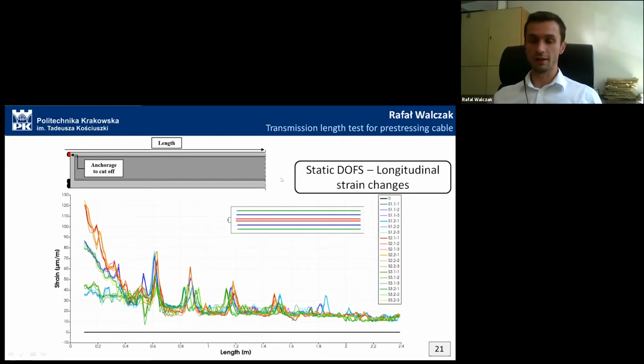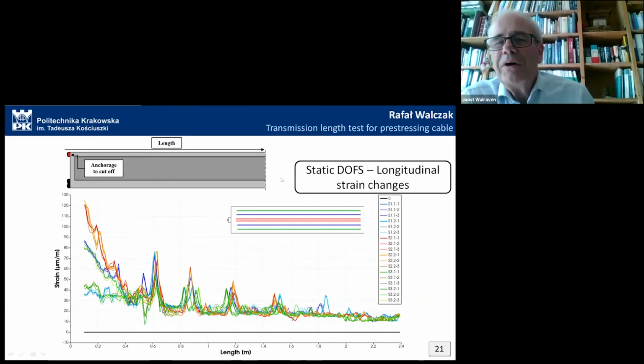And later on in the research, it is planned to study how the transmission length and the losing of the anchorage result in the capacity at shear, because the crane beams, of course, can be loaded nearby the support, so the vertical forces are very high. We will observe first of all how the transmission length goes with these tests, and then how the capacity is lower, and it is lower, of course. Yes, you now have more information because you have opened the ducts, and you have shown that even two wires were totally unbonded. So if you know that, then I think you can also conclude on the anchorage length, but then only, of course, for this particular case.